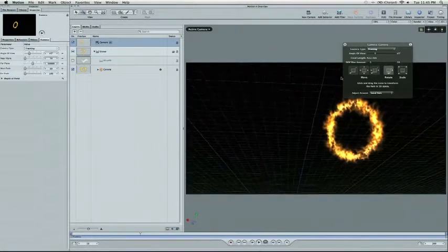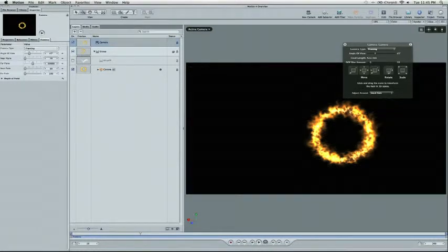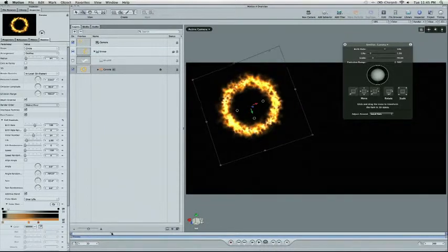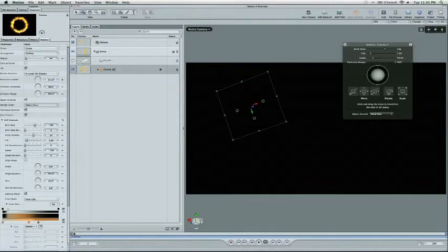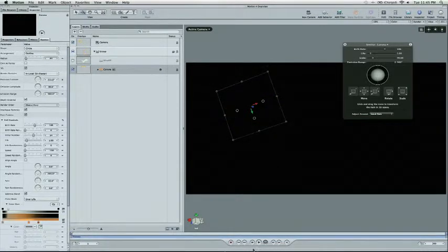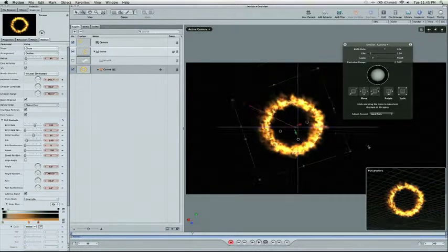Now let's do something else here. I'm going to take away the view of the 3D grid. Let's keep our corona fire up here and animate it. I'm going to drag it here to when it animates on. That's the birth rate, how fast it comes on, because it's a particle. So I'm going to record from there to here, 98 frames into it, and I'm going to drag it down its position.